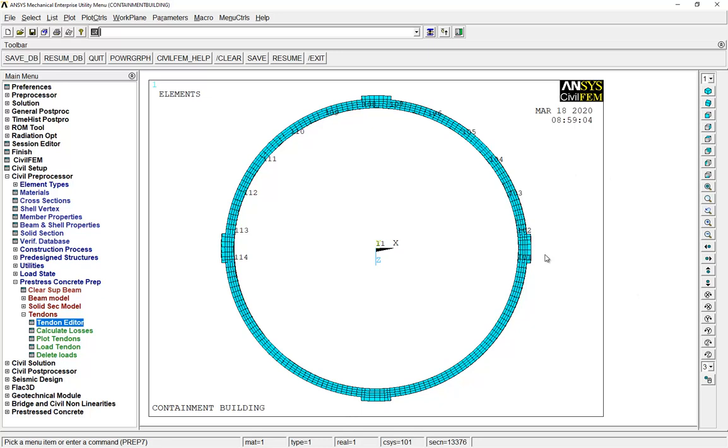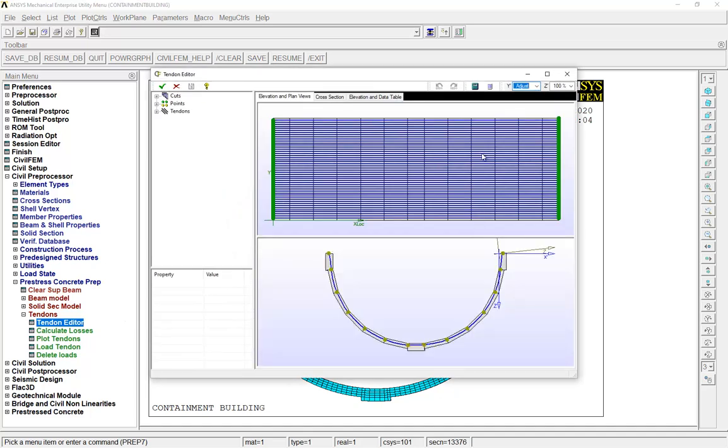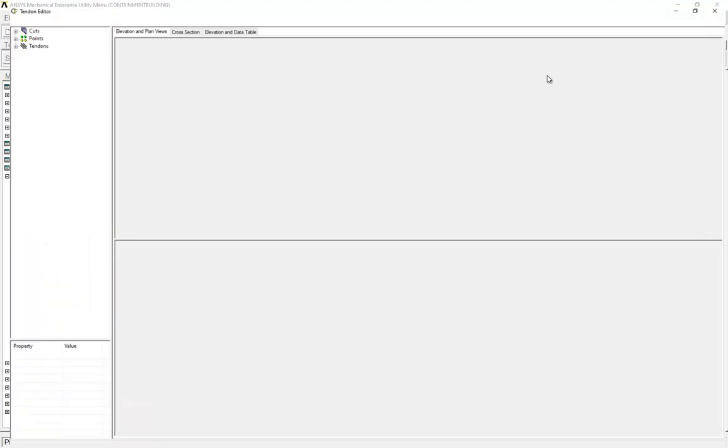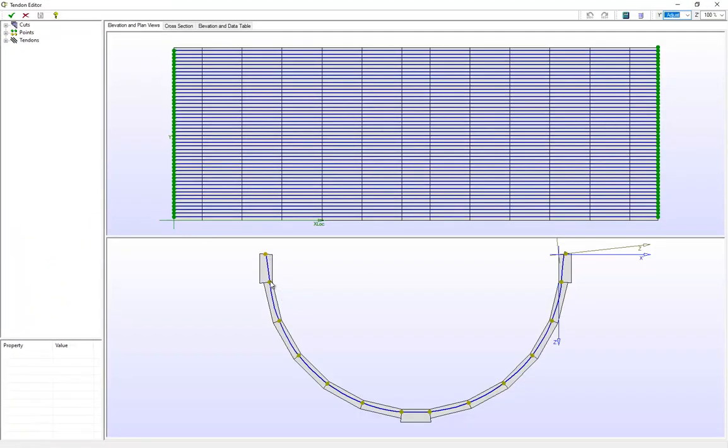So I will perform this procedure 4 times, one for tendons that cover this half, the other for this half, and in the middle we will repeat these tendons in the vertical direction, and also we will put in the middle of these tendons 2 other families that come from this buttress till the other zone, just covering the other half. So well, first I have launched some macros, and the first is, as you can see here in this half, define tendons in this way.